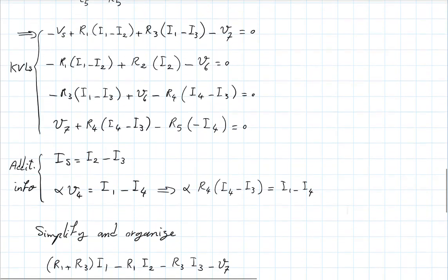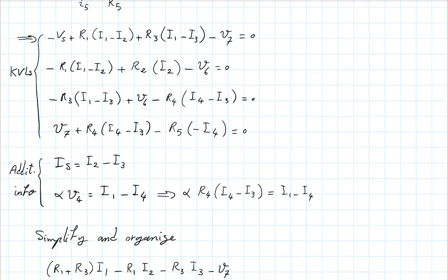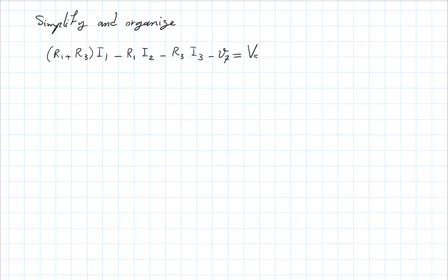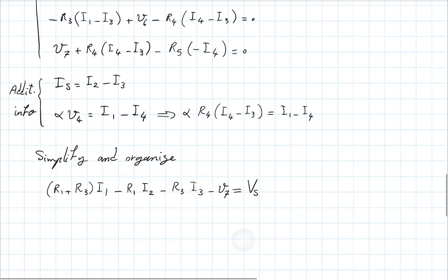And then the known quantity there, Vs, which was a parameter of the problem, I'll bring to the other side. Big Vs. That was just the voltage of the source. And by the way, when I say known versus unknown, of course, in a given problem, you could give me a mesh current and say Vs is unknown. You know, work the other way around. But it doesn't matter. In this case, let's assume you know Vs and you're trying to calculate mesh currents. So that's the first equation.